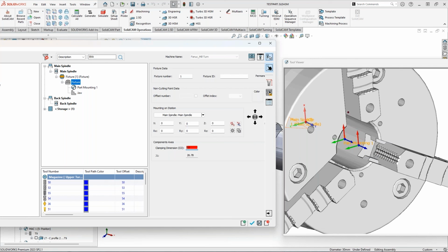Let's move forward. If I have a custom fixture made in SolidWorks and there is a design change, if you alter the SolidWorks fixture model, will it carry over into CAM? Okay, good question. If you change your fixture CAD and this CAD is selected as associative, it is going to be changed in your specific CAM part.